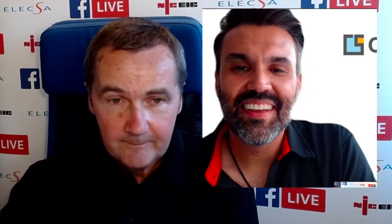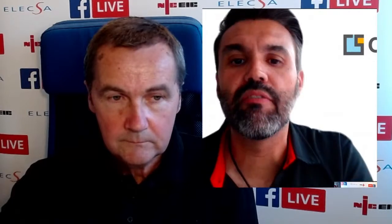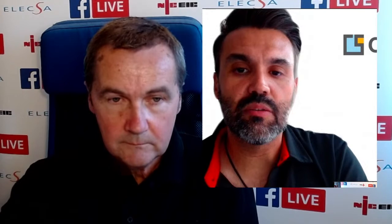Yes, this is actually very popular. I've found it many times on assessments as well. Obviously, the first thing you should always do is advise the customer to contact the DNO, because it might be an inherent thing that they're fully aware of, or it might be a new fault that's developed, which they should be made aware of anyway. So always let them know. For the installation side of things, you need to consider, well, how high is it?